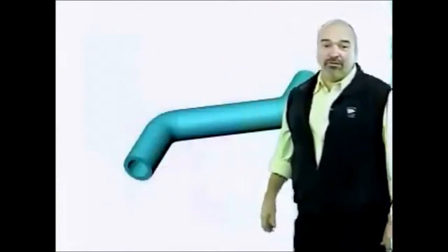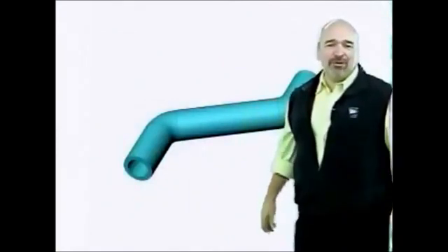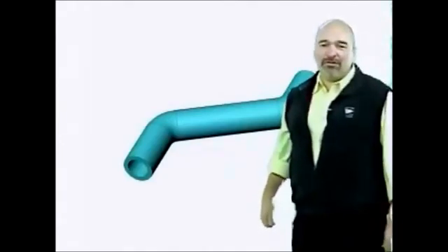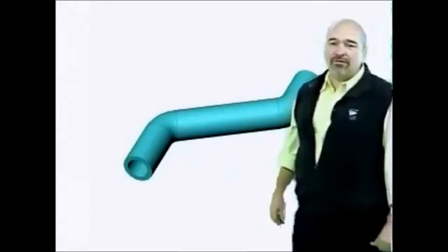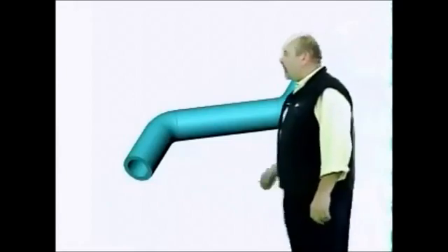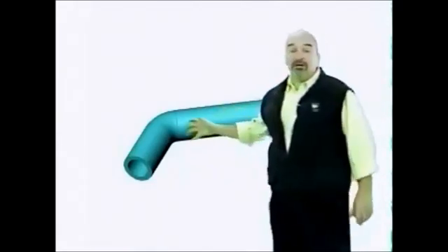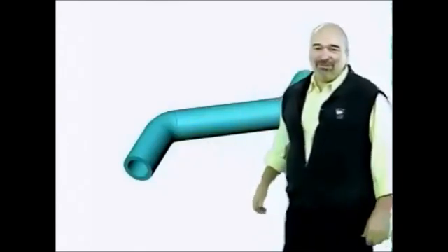Don't be surprised if you don't find your parts in the Y14.5 standard. The standard is a collection of building blocks. There are an infinite number of ways to combine these building blocks to control your parts and still be in compliance with the standard. The standard does not, for example, specifically show how to tolerance such parts as preformed hoses, tubes, and bent rods. However, the building blocks for controlling this sort of part are found in the standard.